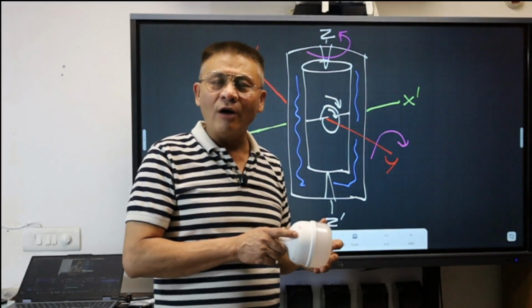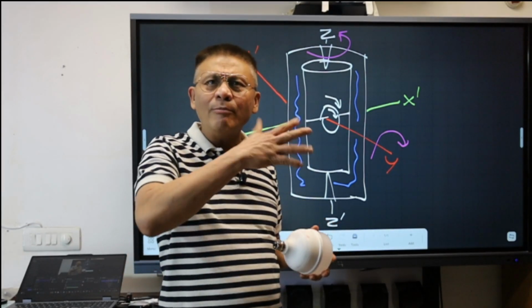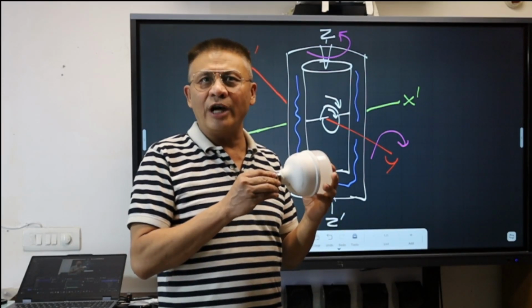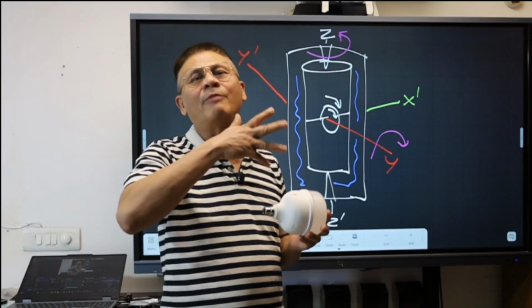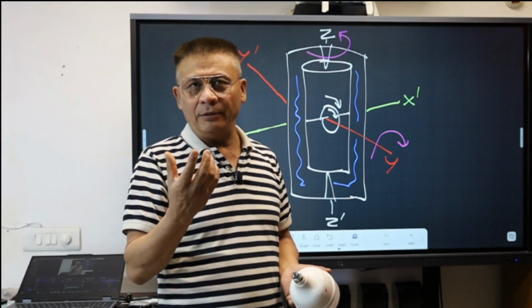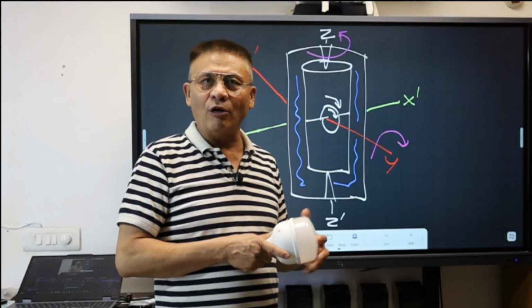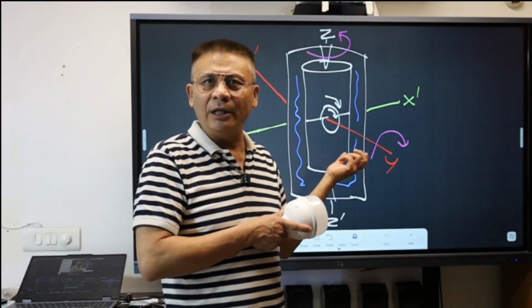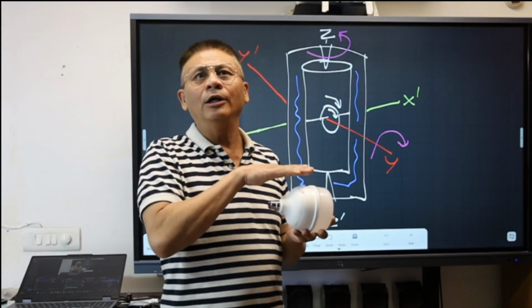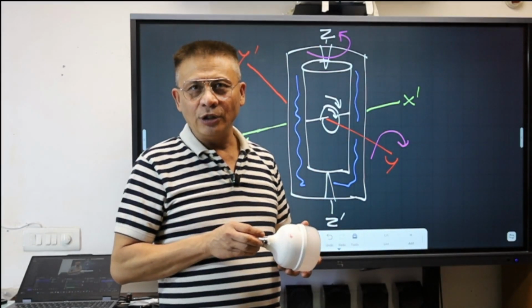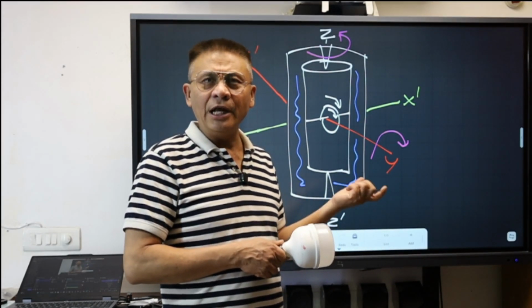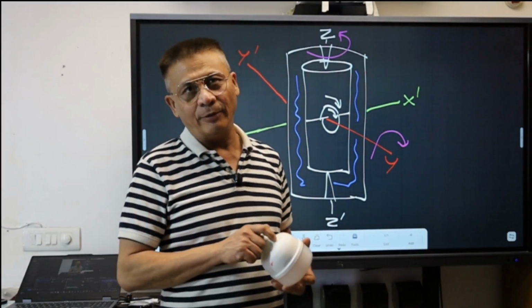So now because of the different maneuvers which are carried out by the aircraft, if any particular gyro or that platform is displaced from the initial position, the amount of displacement from the initial position or the initial alignment can now be determined with the help of this gyro, and that platform can be driven back to its initial position. So this is the use of the rate integrating gyro in an INS to stabilize the platform.